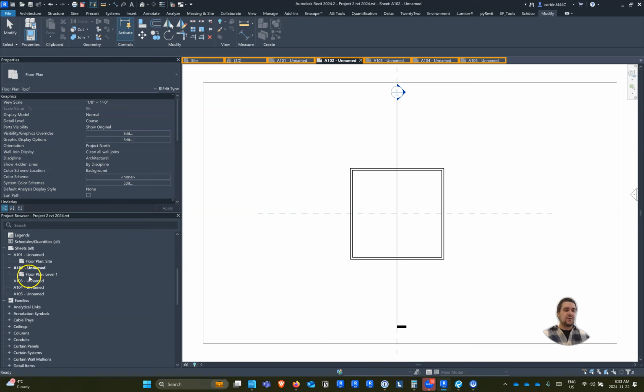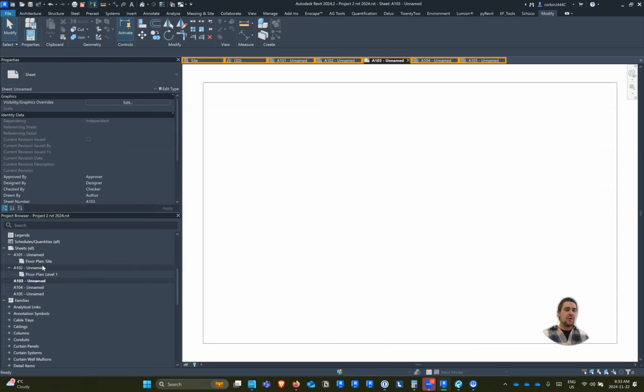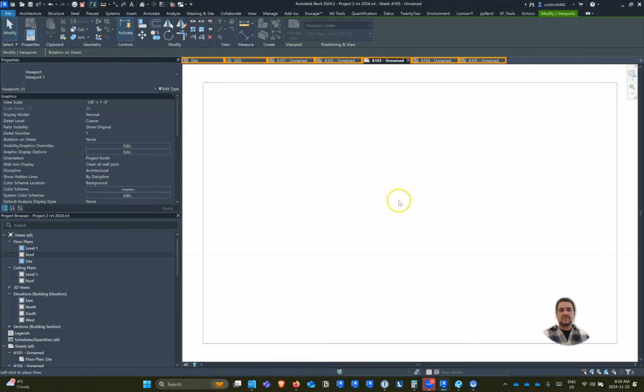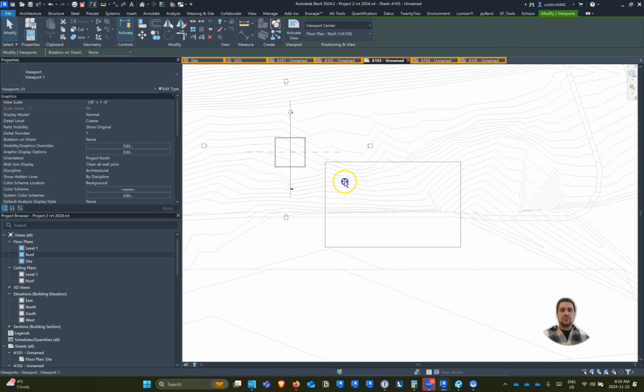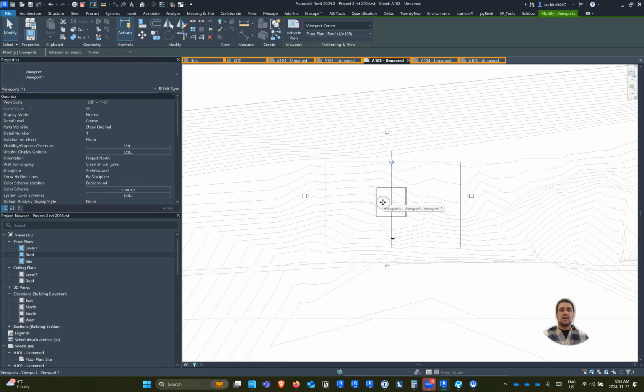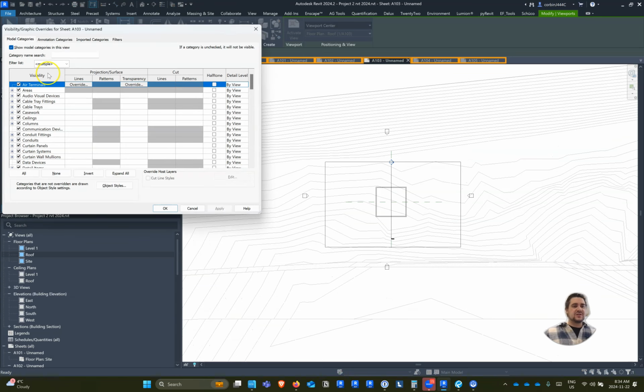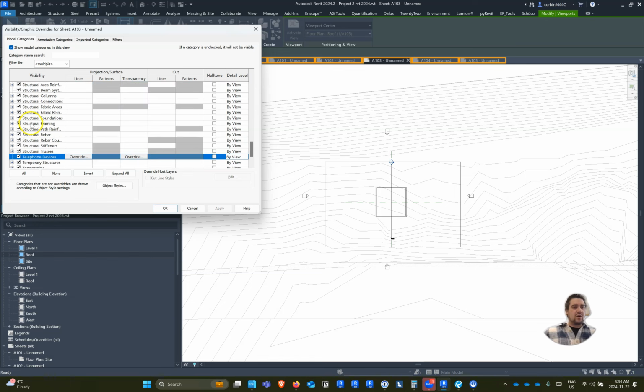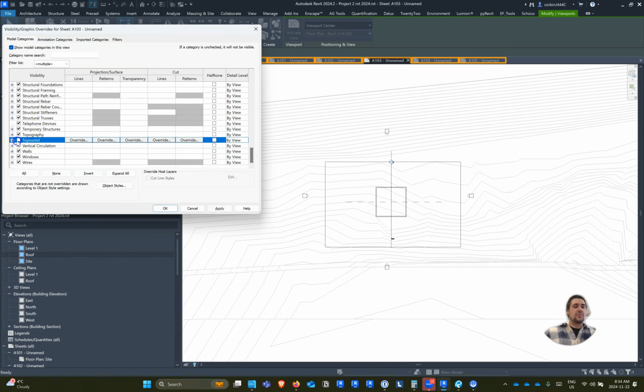I think roof plans are not always required for projects like this, but sometimes they're really nice to see what's going on. And with our two floor plans, let's just go to VG for a second. We're going to go down to our topo solids. We're going to turn off our topo solids because we really only want to see our topo solids in the site file. We don't need to see it in every file. So I'm going to turn off the topography and the topo solids, just in case you're using 2023, not 2024.